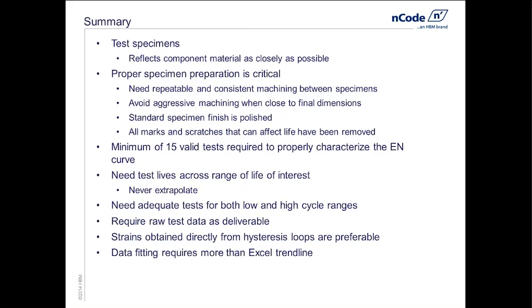The preparation of the specimens is critical. We want to guarantee that we end up with a specimen that is dimensionally correct, so there's minimal variation across specimens, as well as a geometry such that when I apply a tension load, I'm not inducing things like bending because of misalignment of the specimen.